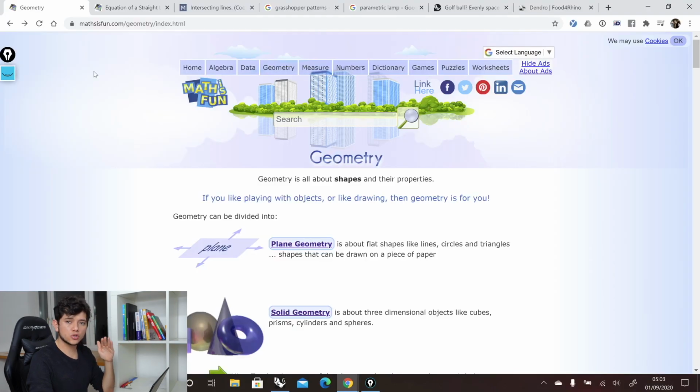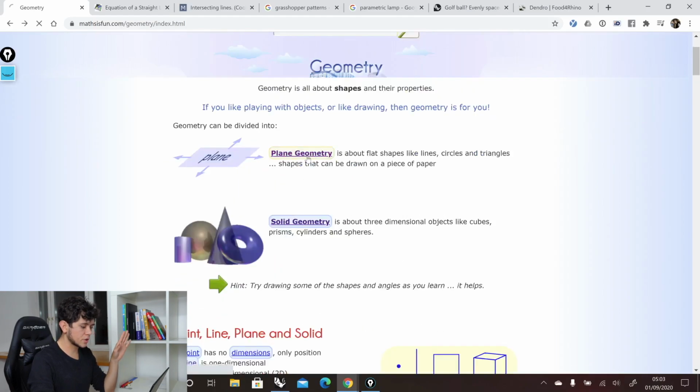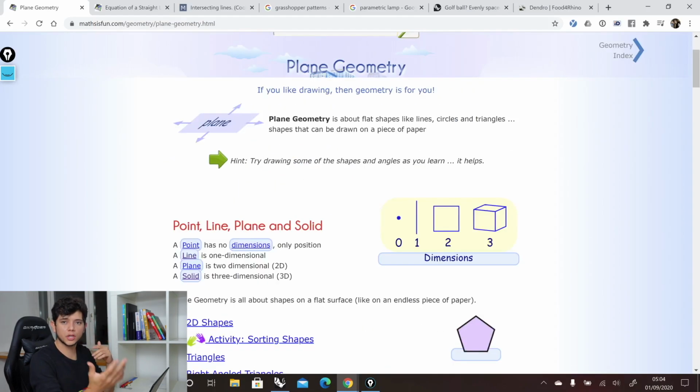If you want to keep your computation time low, you want to look into planar geometry. Of course, the simplest computation that you can look into is points, then you can look into lines, planes, and then solids. Solid operations should be seen as the last resort if there is no other possible way of computing one section of your definition. However, there is normally always a way to make definitions faster.